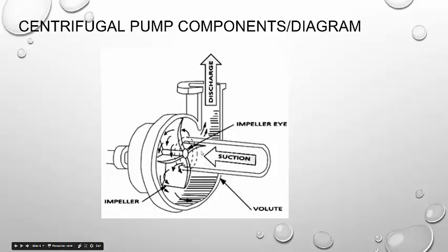We have a suction end, right? We have to have a suction end. We also have to have a discharge end. So water goes in through suction, out through discharge. Make sure you get that straight, right? The last thing you want to do is try to operate a pump in the reverse orientation. So make sure that you're not connecting the suction end to the discharge end and vice versa. Typically you can't, but I'm supposing you could. So let's make sure that we're not going to run into that problem. Suction end here, discharge here, and then we have an impeller.